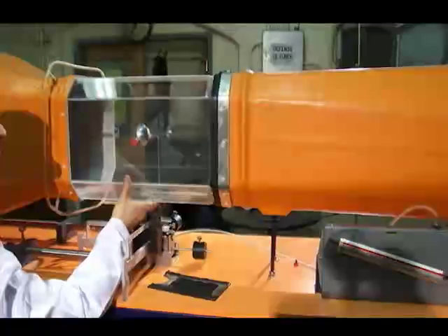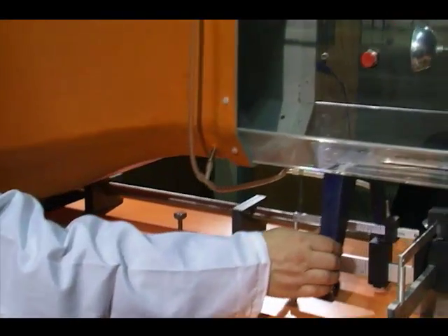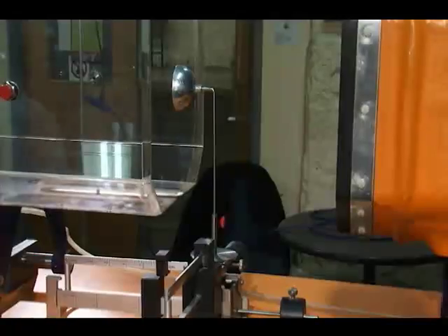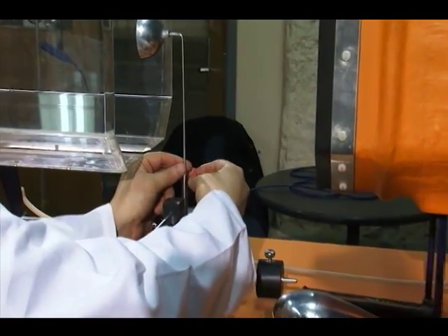The contraction cone chamber contains an aluminum honeycomb flow straightener, designed to ensure that the flow is steady in both magnitude and direction, and it has a flat transverse speed profile. All models are to be tested in the clear acrylic parallel test and measurement section. To fix and exchange the testing models, the testing section can be opened and closed using a sliding guide.